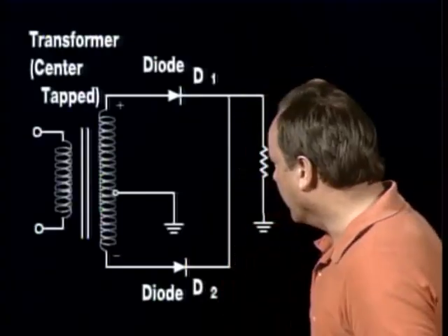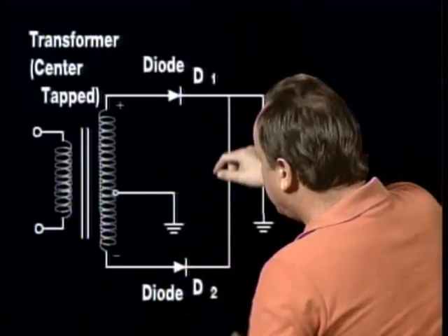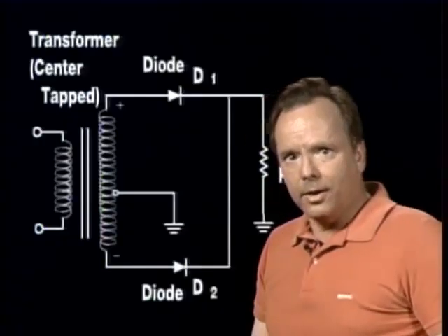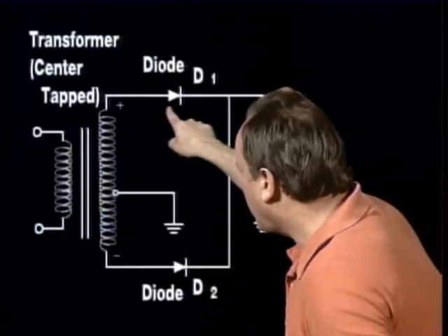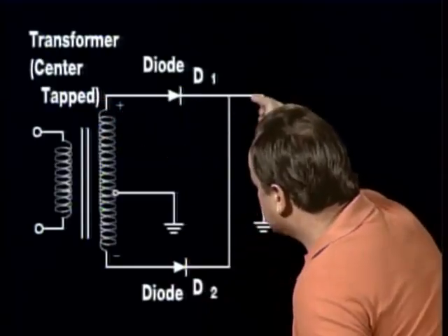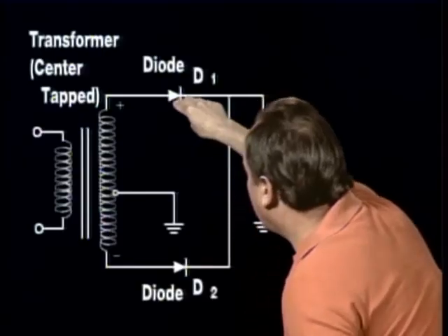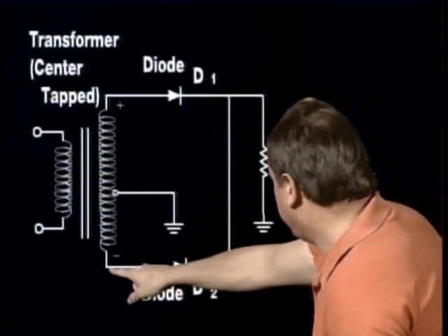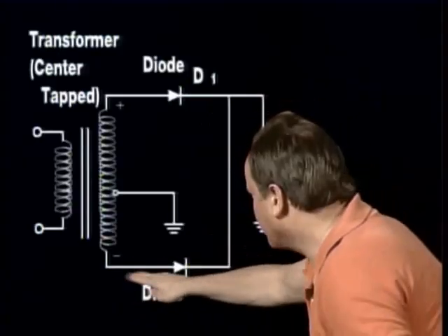Now, a rectifier is a circuit that converts alternating current, which reverses itself periodically, to direct current. You can see how it would work. If you have alternating current that's reversing itself, this diode lets the current go this direction, but not that direction. So what you have now is intermittent direct current. Now, if you had opposite phase alternating current down here reversing itself,